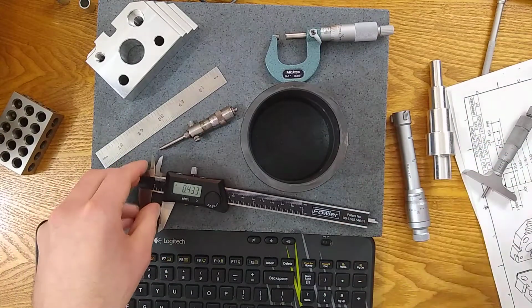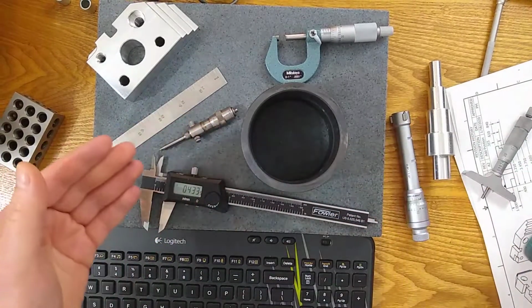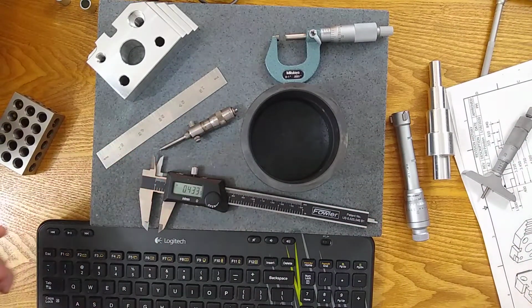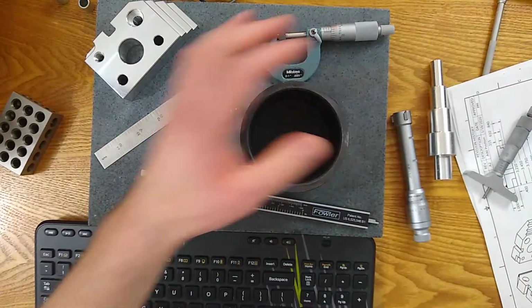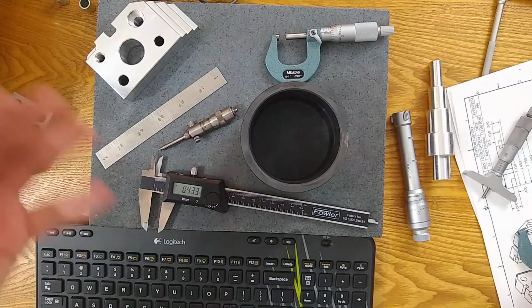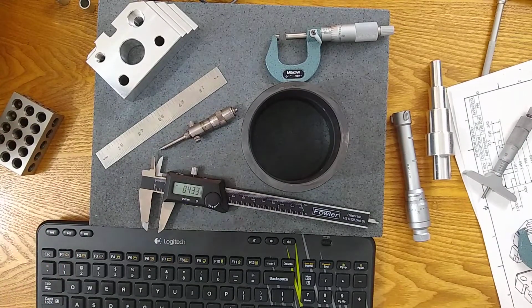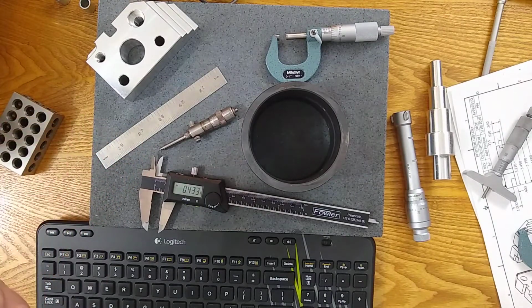Let's grab a more accurate tool. So we grab our more accurate tool and we're like, oh, we're right on the edge of tolerance. But because of the gauge accuracy, we haven't gone out of tolerance. The part passes. So the less accurate tool couldn't verify it, the more accurate tool could. And this scenario I'm going through, in industry, sometimes it's going above and beyond what's required.